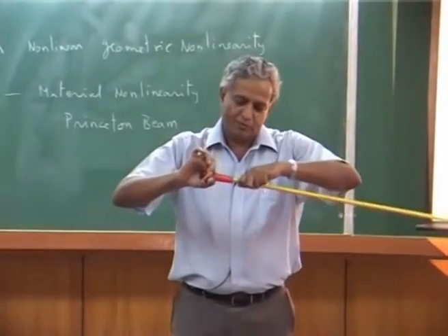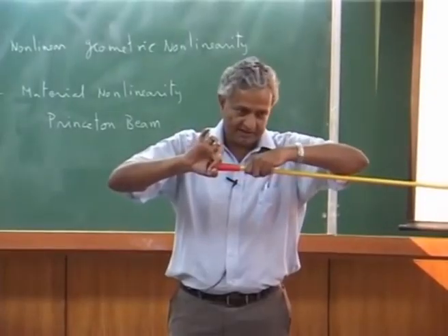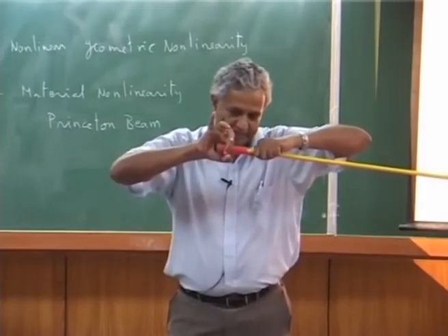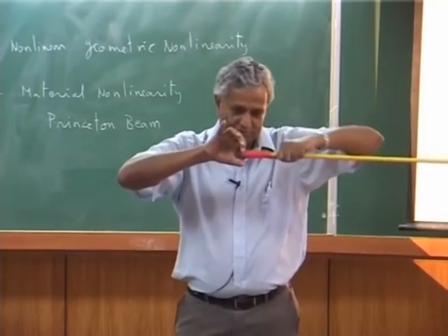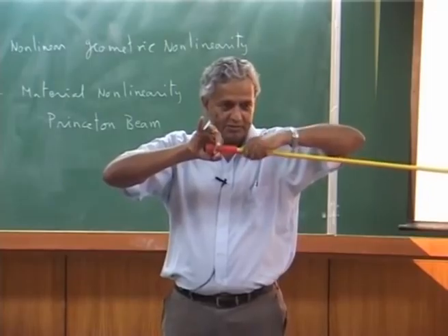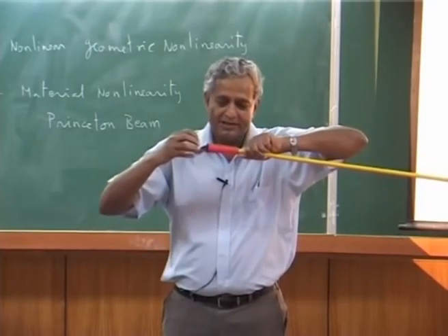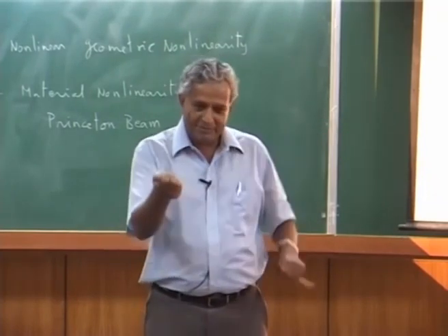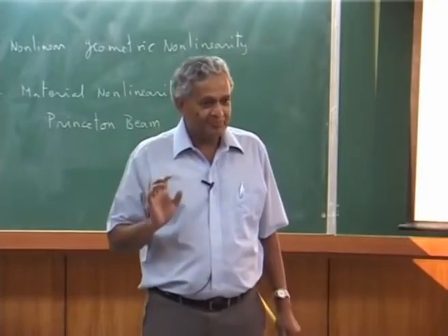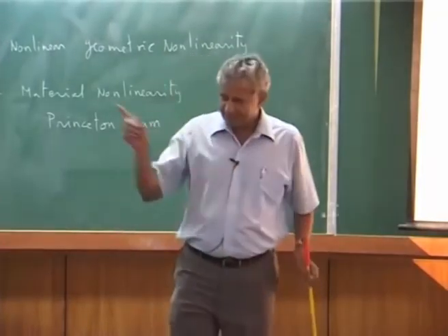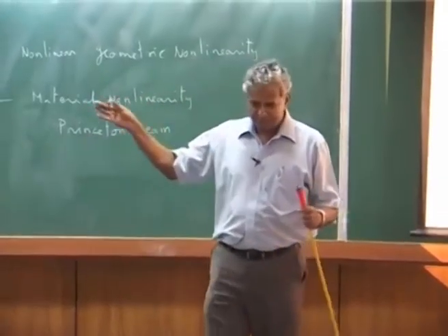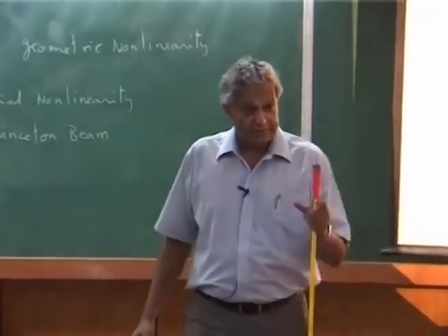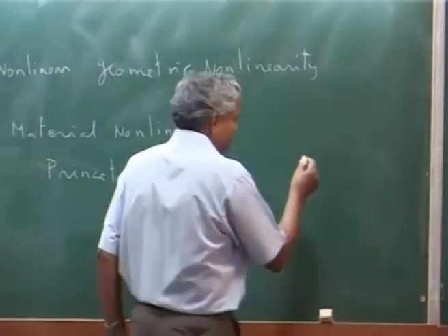You hold this, okay, I am pulling it. If I hold it here, I am pulling it. Centrifugal force will pull the blade, I have to somehow hold it, but when I pull the blade, it should not come out. So I have to put a stopper, but at the same time I should be able to rotate, right. So this kind of bearing is called the thrust bearing. It can take the axial load, but at the same time you can rotate it freely. If you want to see, we have removed our assembly, we can again easily remove the blade and show you how it is assembled. Very simplistically, you can have a